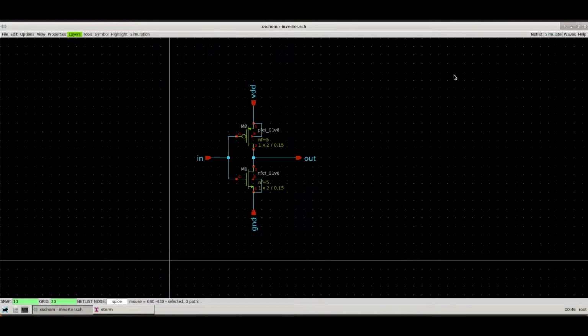The second option is going to be manually creating it in KLayout. And personally, I prefer this method over the Magic method because the Magic method simply instantiates the PDK P cells from the netlist, and it does not take into account dummy devices or any matching that you have set up, which is a very analog specific thing. But it also does not route, so all it does is create all the PDK devices, and that's about it. And this is very easy to do in KLayout anyway with the P-cell generators, and it only takes a few minutes. So we're going to go ahead and show you how to do that.